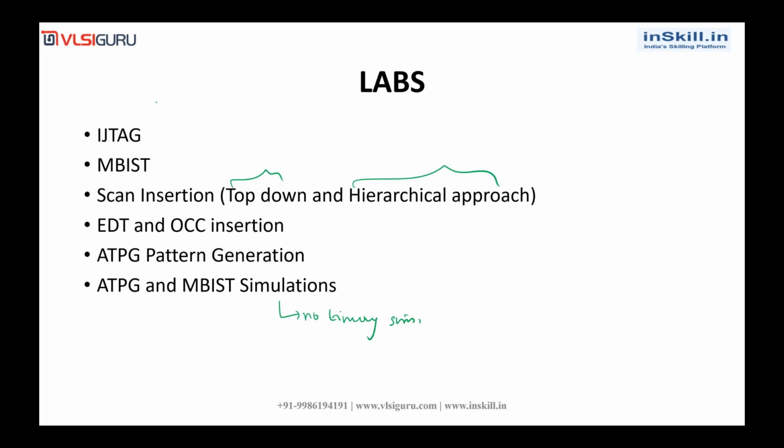JTAG insertion, MBIST insertion, scan insertion. So there are two approaches. One is top down, the other one is bottom up. That is nothing but hierarchical scan. EDT OCC insertion, ATPG, and MBIST simulations. So we will be doing only no timing simulations.